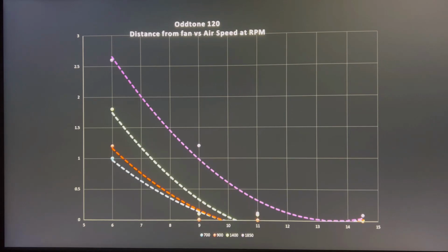So in my opinion, the best case fan design in the world would be one that creates basically a cylinder shape of air that blows straight behind a fan, meaning that the fan would blow air at whatever its RPM was, or airspeed was at the very beginning, and would be a perfectly flat line front to back. But we don't live in an ideal world, and there are going to be aerodynamic losses due to the resistance of the air inside your case, the box. So you're going to experience loss. So you want that loss to be as slow as possible.